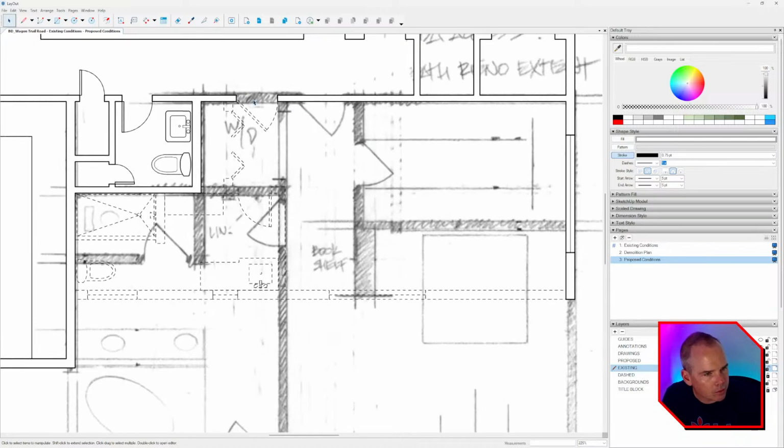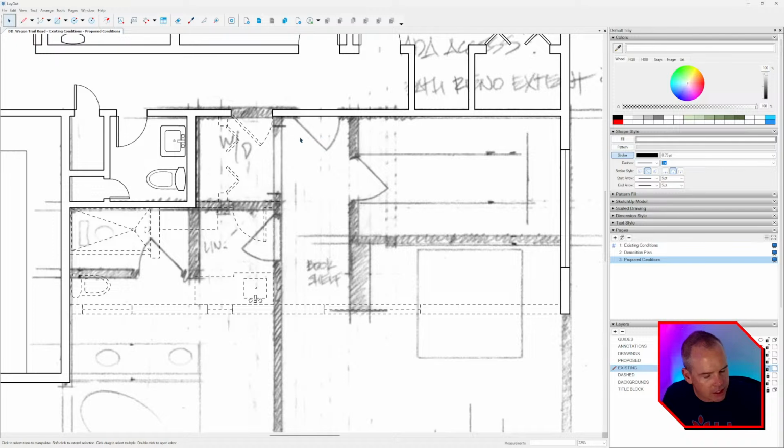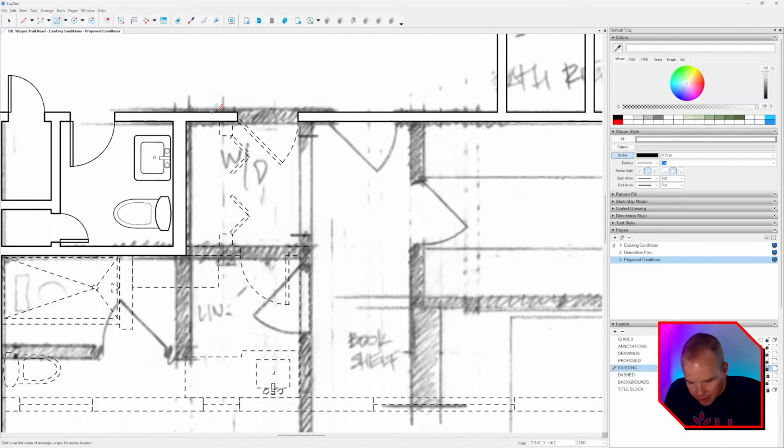So we're going to fill in some new walls. All right, so then I can use just my rectangle tool. I tap S, and I can sample the shape style settings of these walls. So I can tell you that you really never want to be messing around in the layout inspectors. Really in SketchUp or Layout, the more time you're spending in any of the trays or inspectors or the dialogues, that's where your time is wasted. If you can get around that with keyboard shortcuts or just sampling, that's definitely ideal.